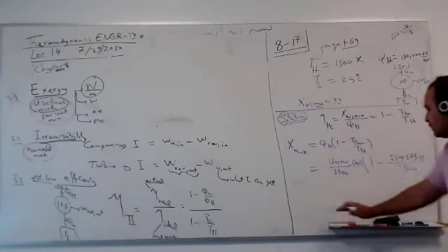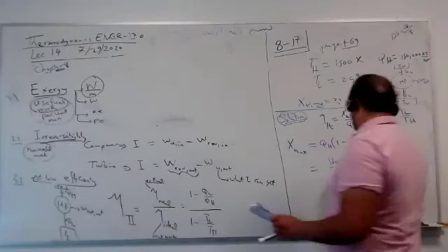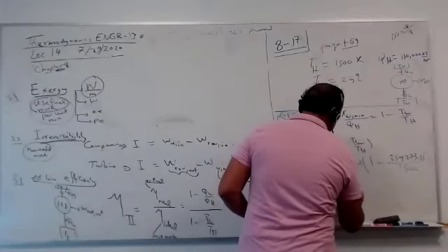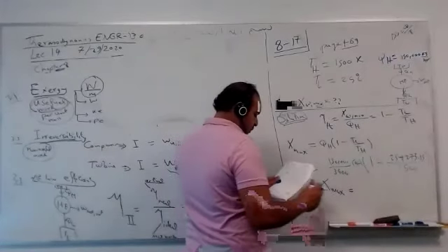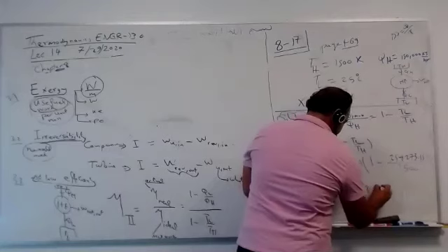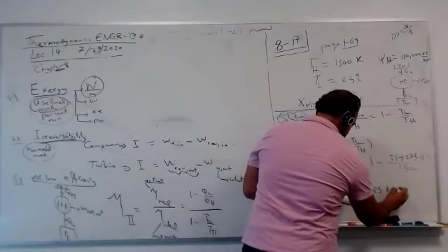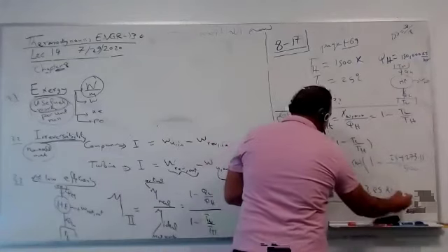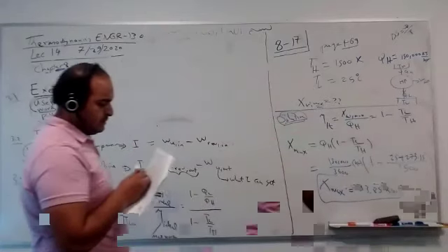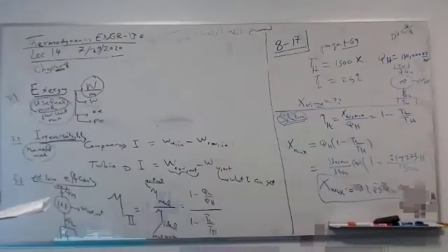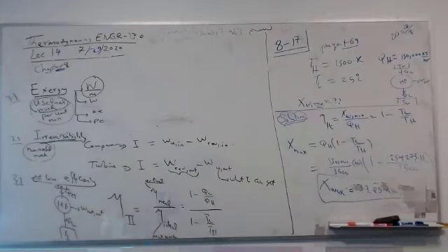Any temperature is Kelvin, just a simple rule. So the maximum exergy, the maximum work I can get, was 33.85 kilowatt. Remember, the heat was much larger than that. So you can get the efficiency, which is like 60%. Guys, what is the second law efficiency here? Can somebody tell me how much is second law efficiency here?